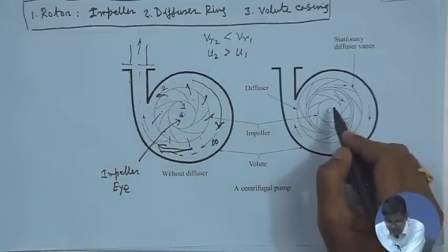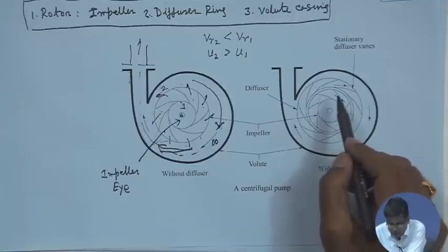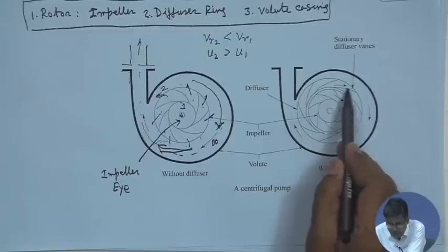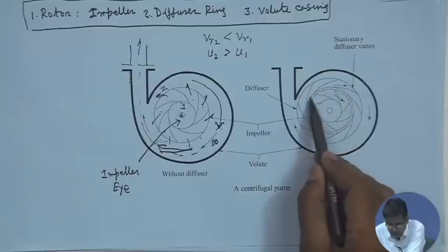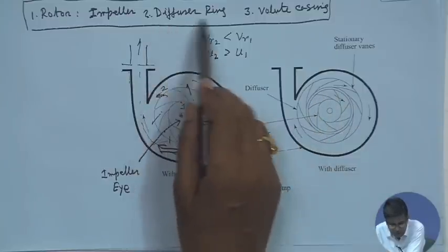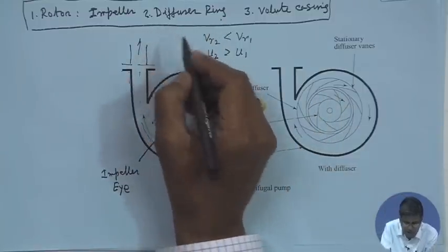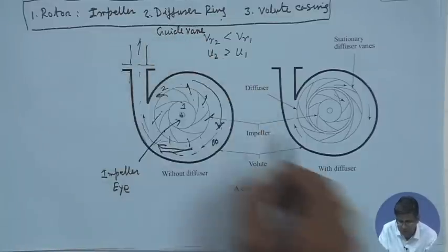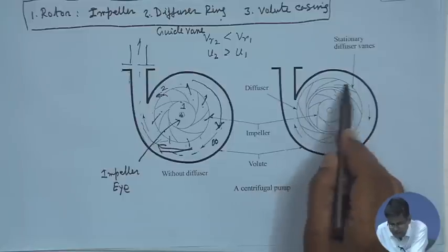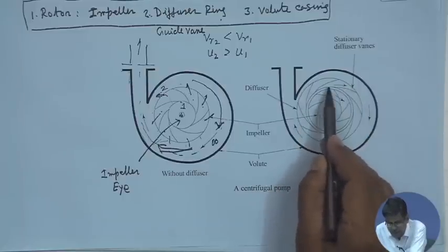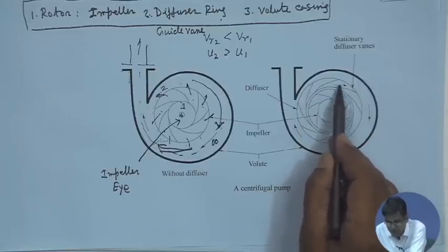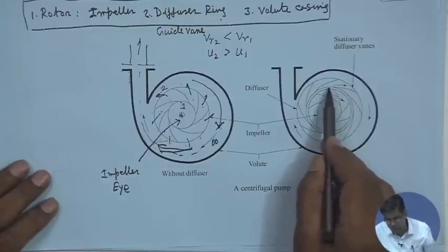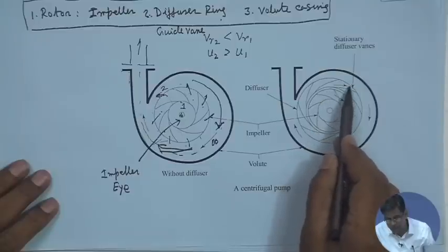But in some cases, depending upon the requirement of static pressure and the flow rate, there are additional guide vanes attached to guide vane rings, also called diffuser rings. These blades are static blades providing a passage that is diverging in nature, which gives an increase in cross sectional area in the direction of the flow, and converts the kinetic energy into pressure energy.